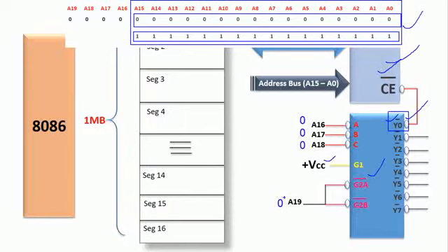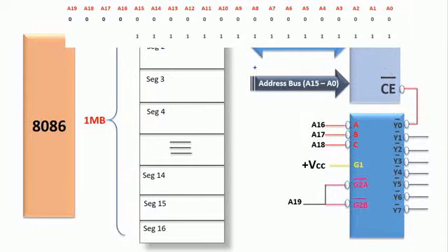Okay. So, when you are applying the A19 bit position as a 0 and A16, A17, A18 positions as 0 0 0, then this particular address decoder is mapping your memory device into segment 1. So here the memory device address is varying from the minimum to maximum.